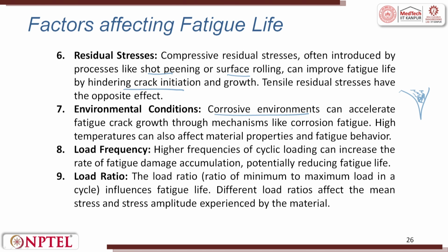Higher temperatures can also affect the material property and the fatigue behavior. Load frequency: higher frequencies of cyclic loading can increase the rate of fatigue damage accumulation, potentially reducing the fatigue life. Load ratio, the ratio of minimum load to maximum load in a cycle, influences the fatigue life. Different load ratios affect the mean stress and stress amplitude experienced by the material.